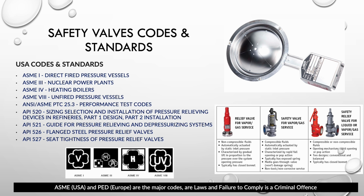Yes. I have again seen on different occasions that somehow a relief valve is being used as a control. They are not supposed to be doing that. Relief valves are there because every other measurement that you have put in place has failed, and this is your last resort. You cannot be using a pressure relief valve to control the process.